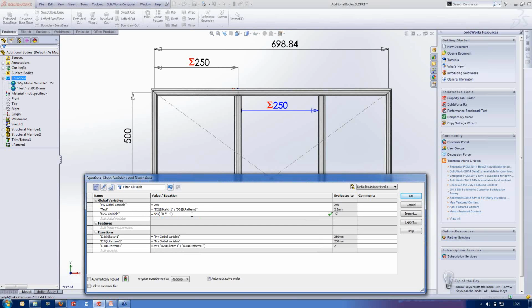Now this can be quite handy if you have any equation which could give a positive or negative answer. So for example, a quadratic equation, then it always gives a positive answer coming out. The reason you might want a positive answer, if you're controlling a dimension, is that dimensions cannot be negative. So it will give you all sorts of errors if you try and make a dimension come out to a negative number and not allow you to use the equation. Absolute then makes it positive, and so allows your answer to be true in both cases potentially.